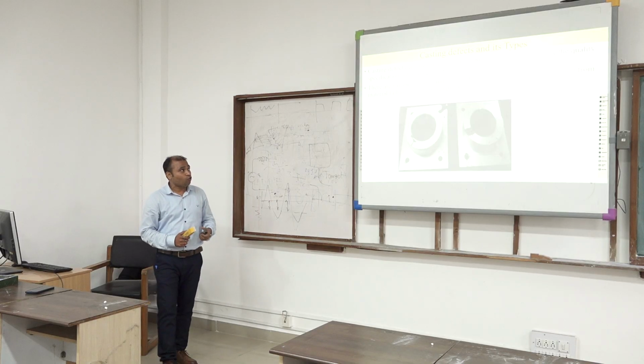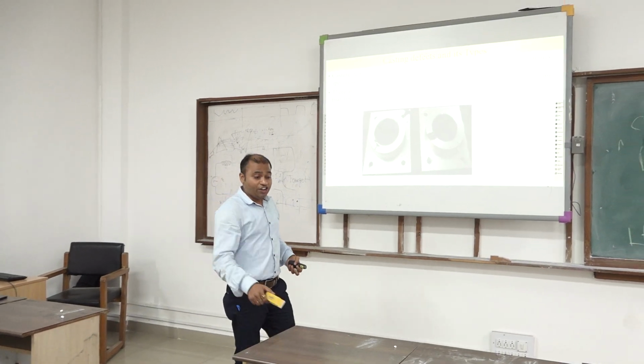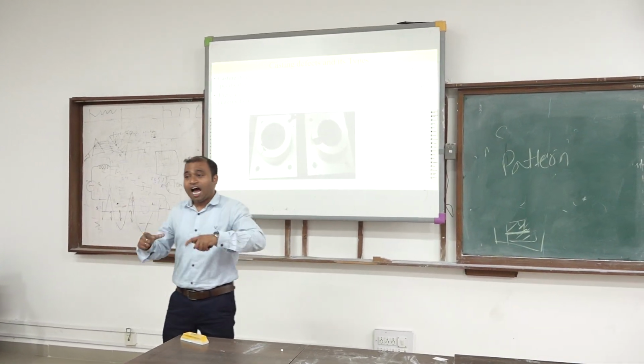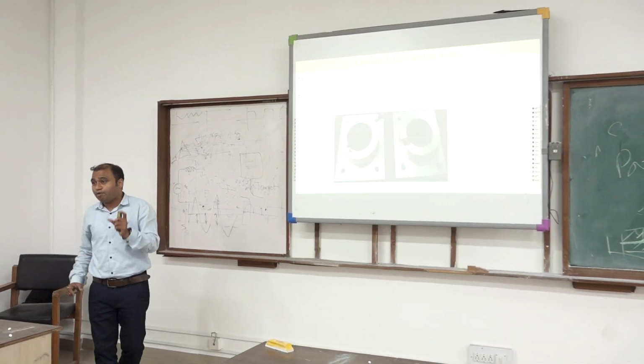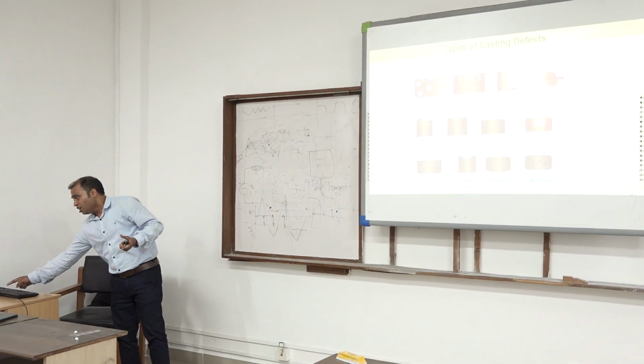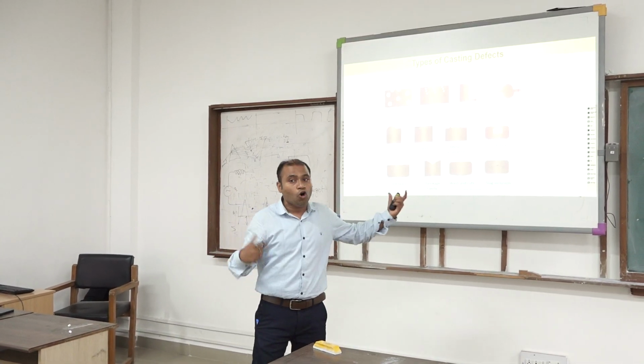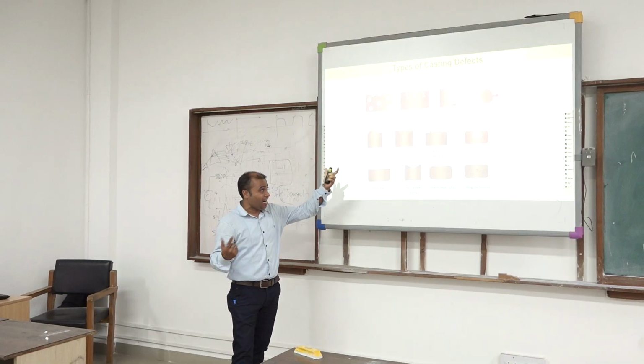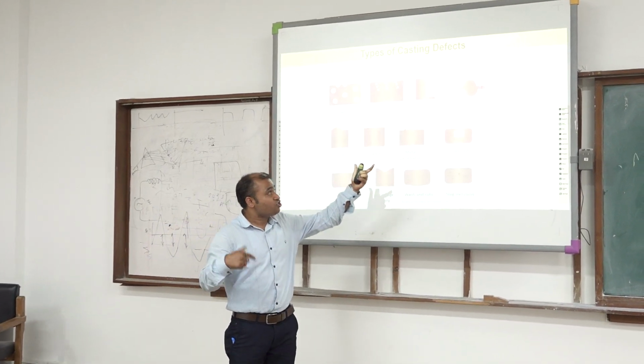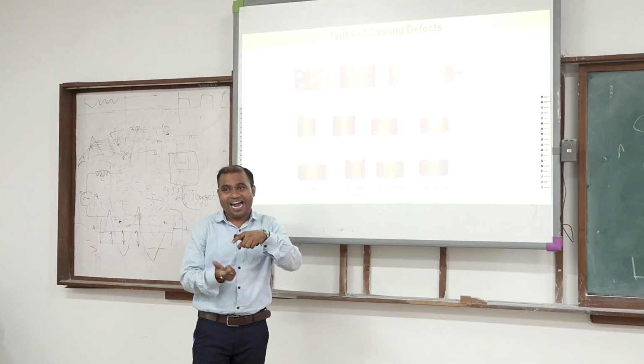Now, I have told that after the solidification occurs, the casting will have some defects. So we should understand some of the defects of the casting. These are a few defects: during the casting some gases get trapped, so blowholes and pinholes will be formed. Misrun is a casting defect. If the cope and drag are not properly